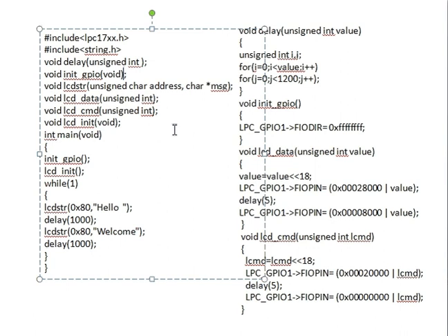16. For that there is a different command which should be passed, then only it will come to know that you are using 16 by 2 mode. And also the pixel area which we have discussed, 5 by 7, that's the resolution provided for displaying each character, even that should be addressed. And also the number of bits you are using, 8-bit lines are used for transferring data from the controller to the LCD module. Fine. So those will be defined in the LCD init function.